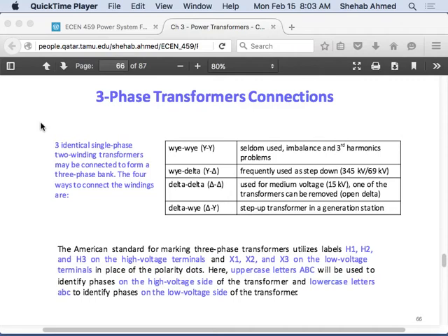So last time we did some examples on the per unit system, and in one example we had a star delta transformer, and someone asked, why aren't we dealing with this differently? I said that typically we will ignore the star delta effect because it does not really change what happens when we talk about equipment rating. It will really affect us when we talk about actual building of the system, or designing the protection system for a certain power system, because what the star delta transformer does is change